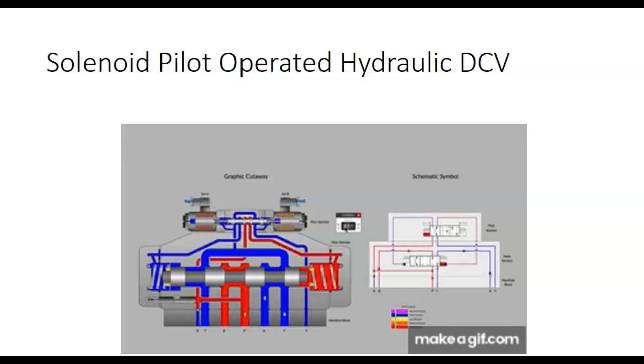So you can see where it's actually, it's got a valve up here. The solenoid moves a small valve. This takes the actual pressure coming in from the system and uses that to shift the spool. And we see this a lot in pneumatics. All the valves on the Festo line show the symbol, but the Amatrol line might use them because it's transparent to you how it shifts the spool. All we know is the solenoid is either doing it itself or it's opening up a little pilot valve that causes it to shift.